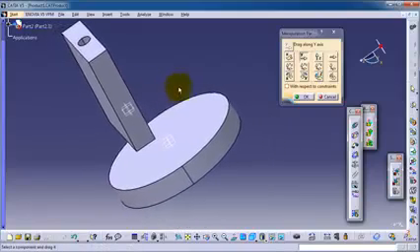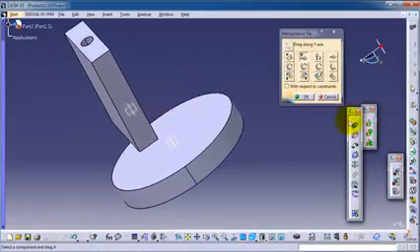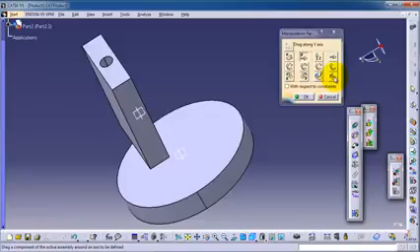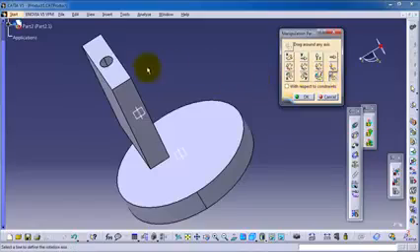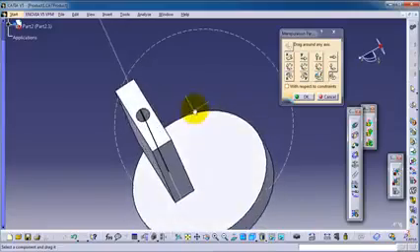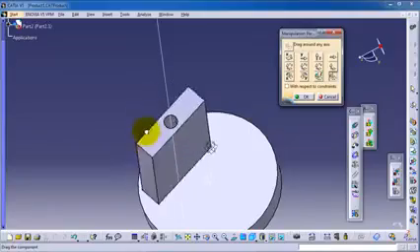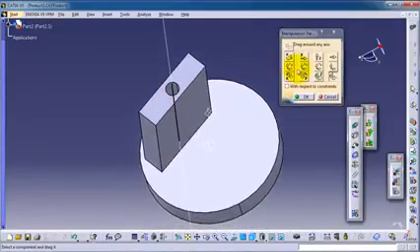So you have an idea how you can use the move manipulation feature, and it is not as accurate as the constraints, where you can specify directions, surfaces, distances, angles. And now another thing I'm going to show you here: you can define an axis outside the original X, Y, Z axes, where you can rotate your part. For example, if I hover over this, I can define that axis in the middle cylinder of this block. Now you are able to rotate in that direction.